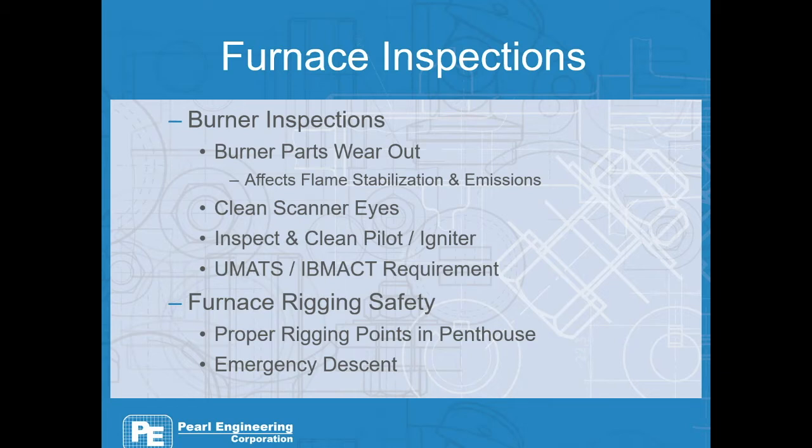One other short thing to touch on with furnace inspections. It is important to take the extra time and plan your furnace rigging. If you're installing a scaffold or if you have swing stages installed, these should be thoroughly evaluated by each person before you enter. You should have a good plan for setting this up. However, they're set up by professionals. Professional scaffold builders typically install them, but it should be inspected.